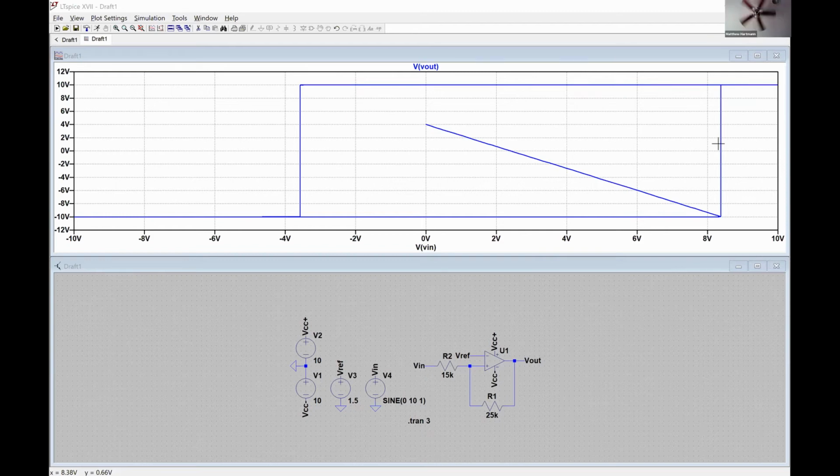So we get this odd looking graph because there's what's called latching. It's holding on to a value until a certain trigger limit is reached. And we didn't see this in our comparators because the comparator effectively doesn't have any memory. That positive feedback is providing a means for this op-amp circuit to hold on to a particular value until a specific criterion is met.